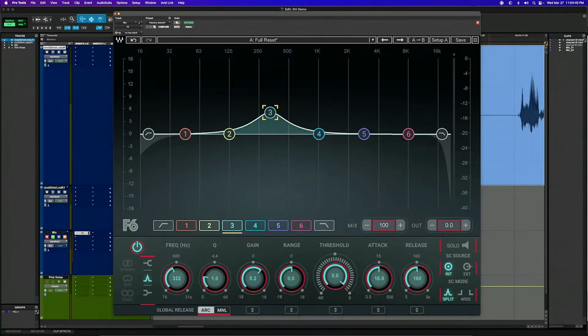Jeff pretty much covered it, but I'll just demo what he mentioned. So you can bring up the gain on an EQ, make it quite a tight Q. And then you can sweep around and find whatever frequency is bugging you, or what frequency range you want to boost or cut. After some time of doing this, especially when you're doing dialogue, you can get a sense of in what range it would lie.